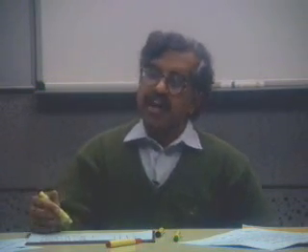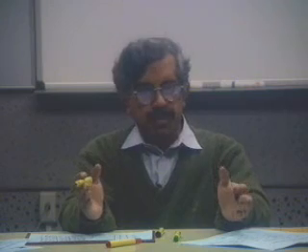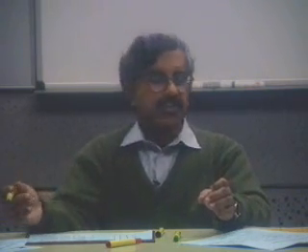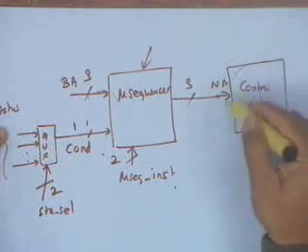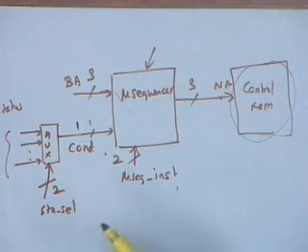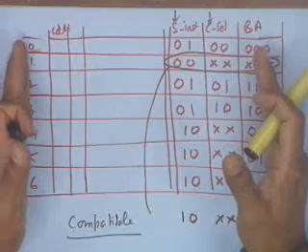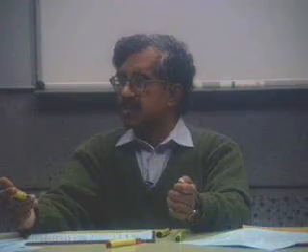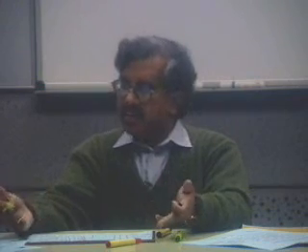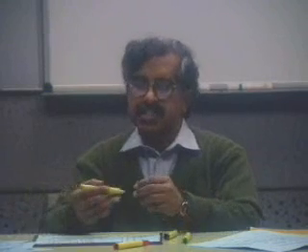So you can use these facts to reduce the number of columns. When you reduce the number of columns, you are effectively reducing the size of your microinstruction, the number of bits in it, which in turn is going to reduce the size of the control ROM as well as the register. It is a very effective technique, so we will talk about some techniques for reducing the width by finding which columns are compatible. Again, we can use graph algorithm techniques to do that. So you can compress this into fewer bits. We will discuss that.